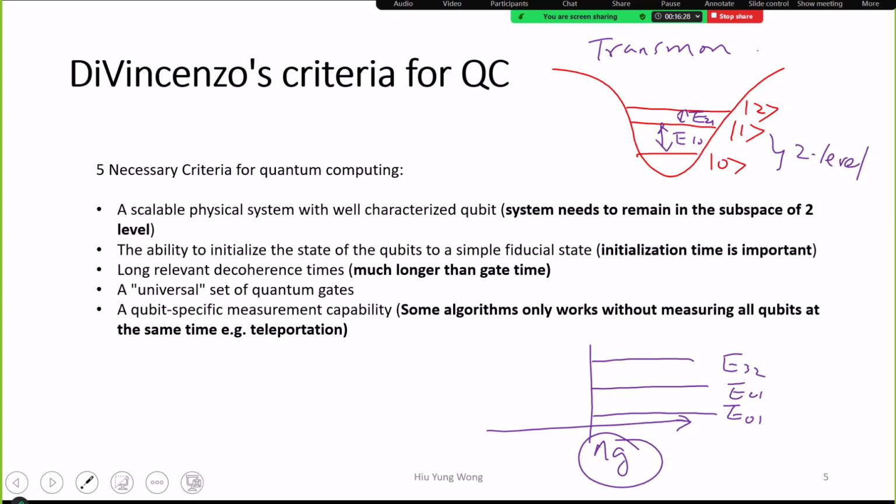So now can someone give the final answer? How do you measure 0 and 1, in the architecture I showed you? You send a pulse to the resonator and then measure the transmitted signal, right? And the transmitted signal only has a big response at the resonant frequency, correct?